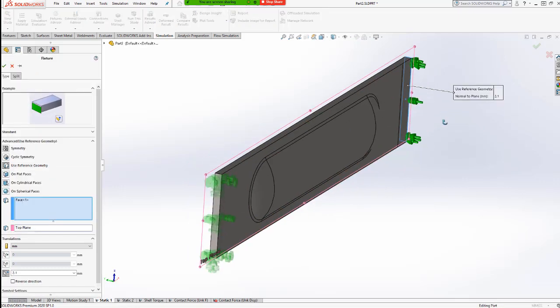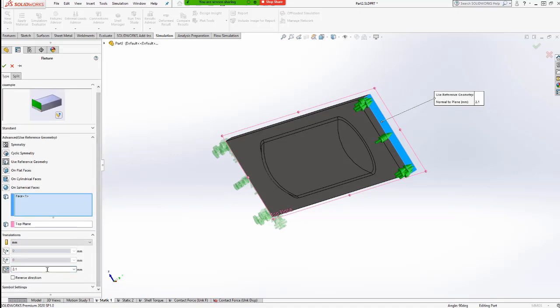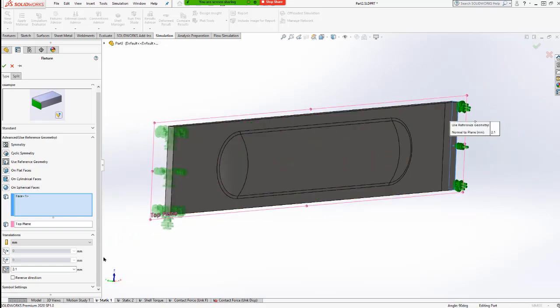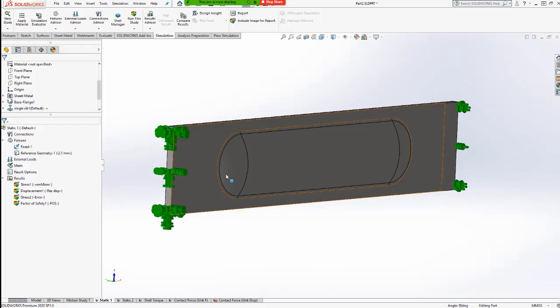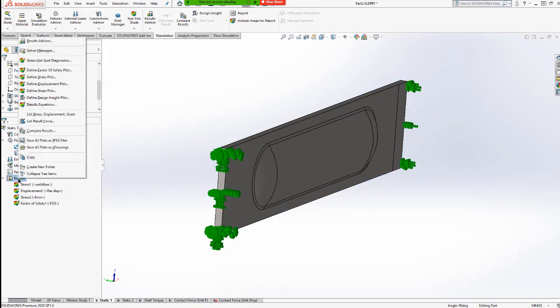And speaking of over here, we have our displacement. And I just said that this is going to be 2 millimeters right here. And it turns out if I move this up to 20 millimeters, we will get a small displacement, large displacement flag. For the sake of example here, I'm not going to do that. I will do that later, and I'll quickly talk about that. Though, since we're not going to be discussing nonlinear analysis, we'll just talk about it, and I'm just going to state that once we get there. Sweet. So I have my study already run. Now, if we right-click our results folder, we can have this option, list of result force.